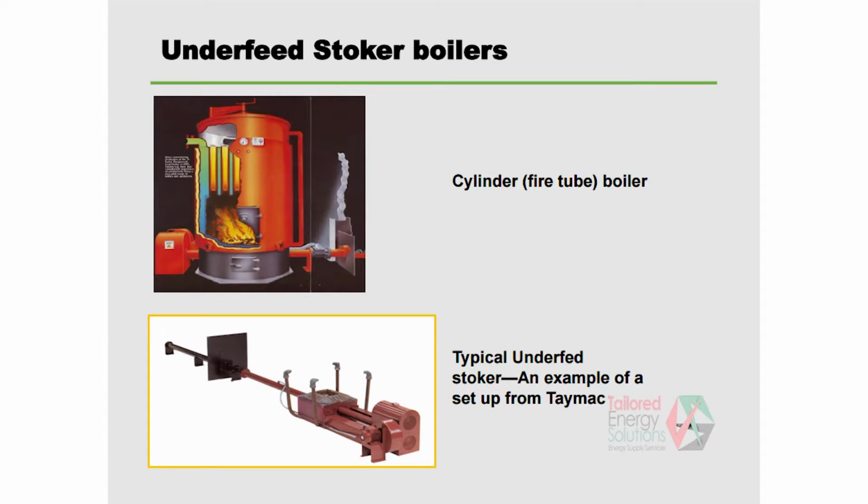The coal feeds through the retort here. Combustion air supplied by that fan pushes through here. Some of the air comes through the holes for burning. A part of the air comes up through the four nozzles as overfire air, which is very, very important to minimize smoking. Another thing I wanted to mention here is that for maintenance, people forget to put a balance pipe through that, taking the air pressure from here, to seal against any gas possibly going that way. It's a very, very common problem here. Some people forget that.